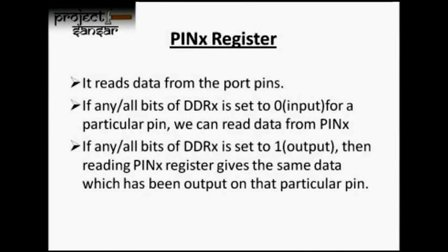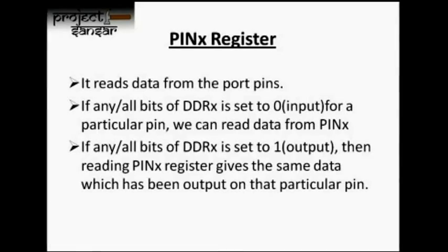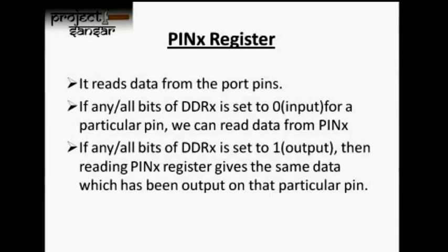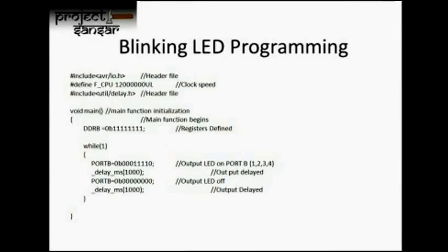The PINX register is used for the purpose of input. So if I write PINB, C or D as 0B00000011, it would read the input from pin number 0 and 1.